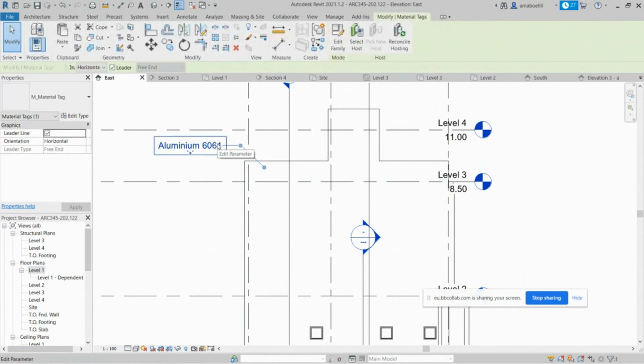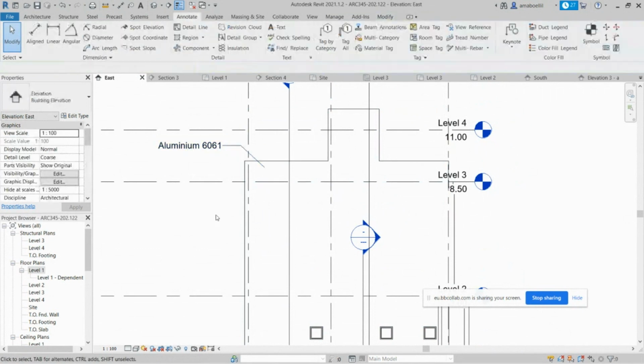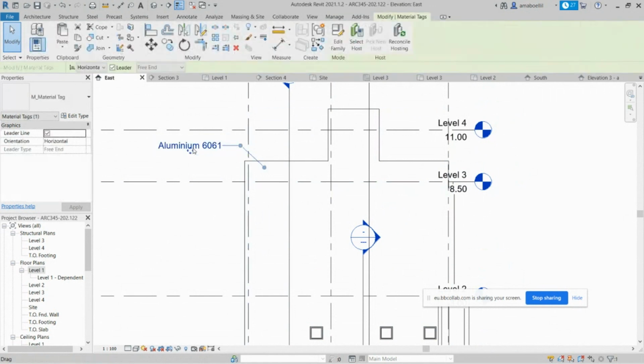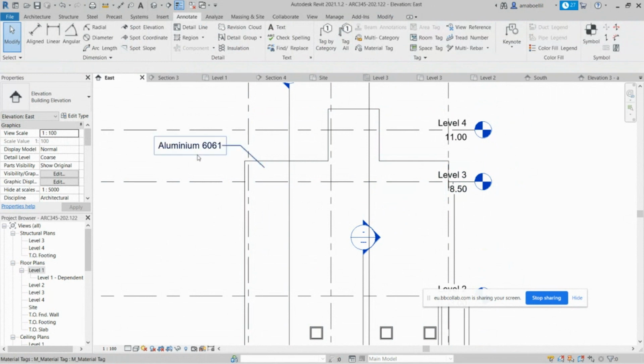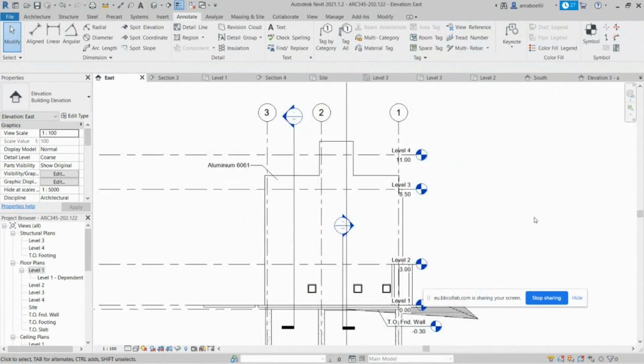I think we will talk about this more once we want to change the material. If you want to come up with your own material, you can still change it and then just edit what you want and add your own ones. Of course, the elevations are going to be created automatically for you. Whatever windows and door openings you set will show in the elevations, and in addition, the heights of the elevation will show up directly with reference to the levels and the sections, tags and lines.